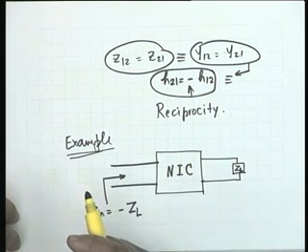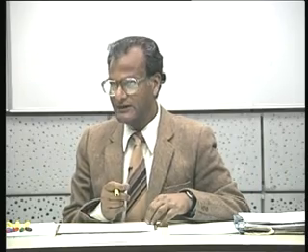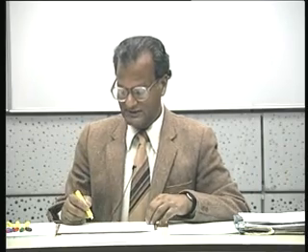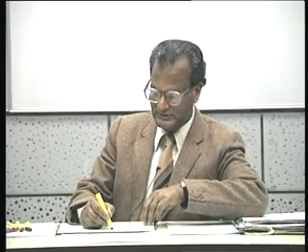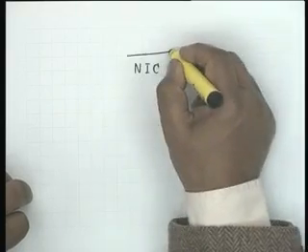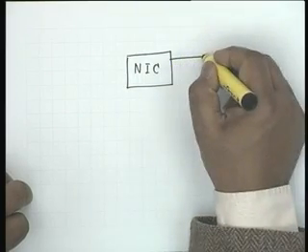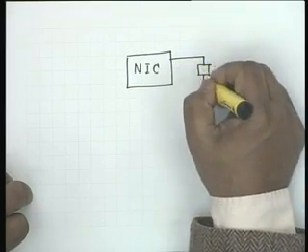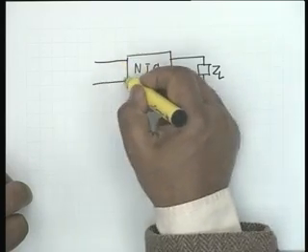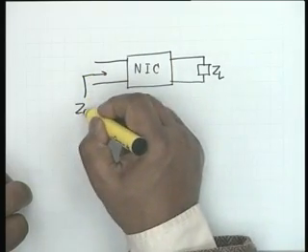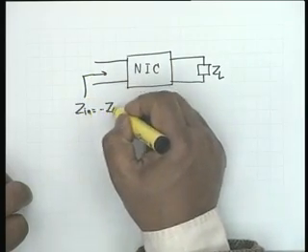Obviously, it converts a positive impedance into a negative impedance, and this is why it is called a negative impedance converter, or NIC. The NIC has the property that the impedance at the input is the negative of the impedance of the terminating impedance. Let us write it again, Z in equal to minus ZL.